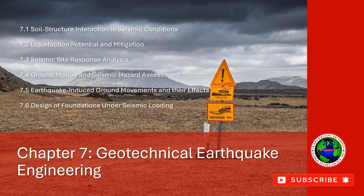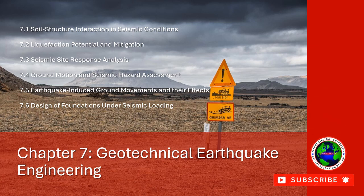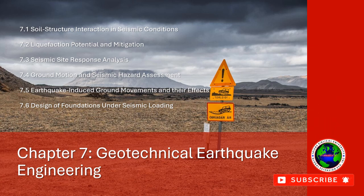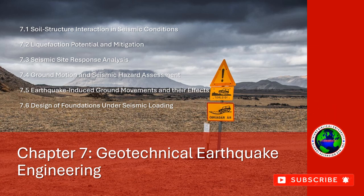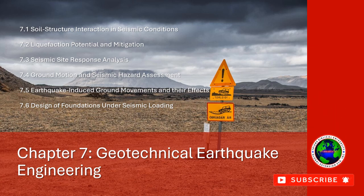Key concepts: foundation soil interaction. The foundation of a structure, whether shallow or deep, transmits seismic forces to the underlying soil. The soil's response can alter the load distribution and the performance of the structure. Wave propagation. Seismic waves generated by the earthquake propagate through the ground and the soil, causing shear strains and displacements.